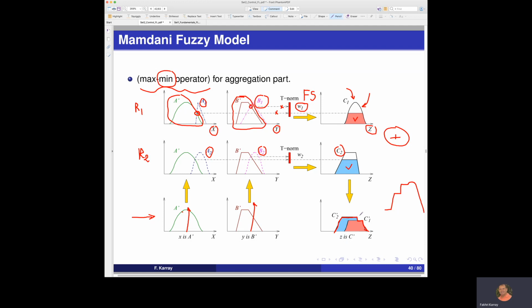So this now is the membership function which is the aggregate of the outcome of all the membership function representations, and it is given by C prime. C prime is going to be the overall value. C prime 2 is due to C2, which is the clipped version. C prime 1 is no other than the clipped version for the rule 1 function of our system. Then we take the maximum, and it gives us a membership function of this particular form in this particular area here.